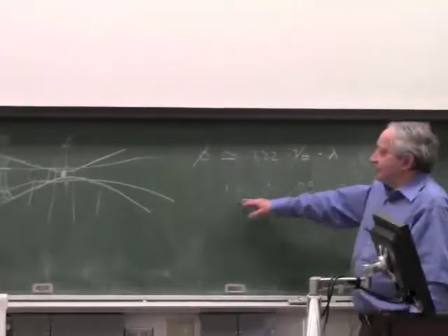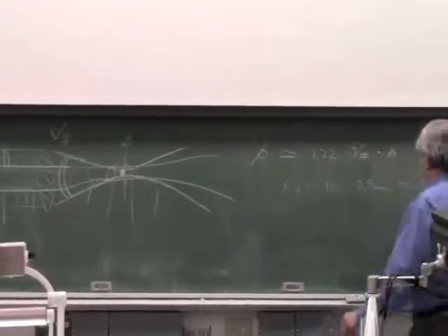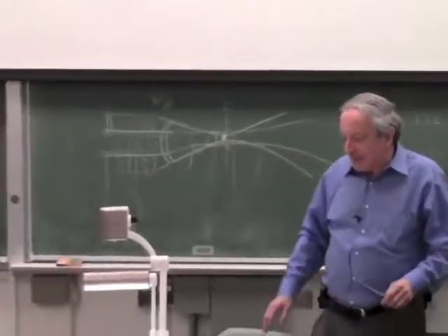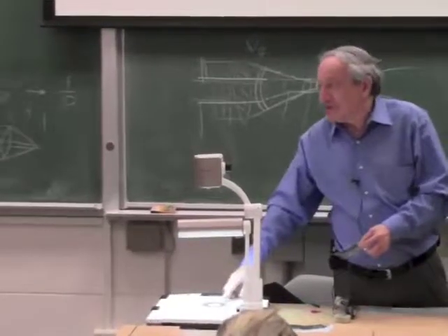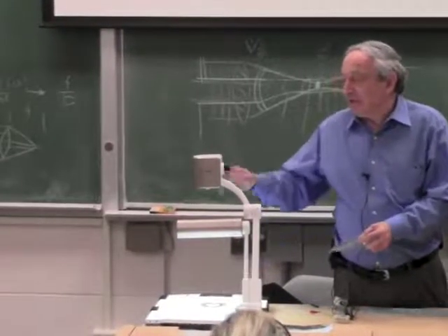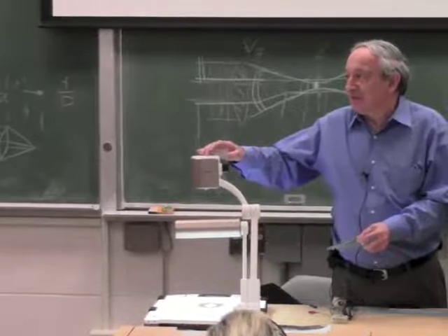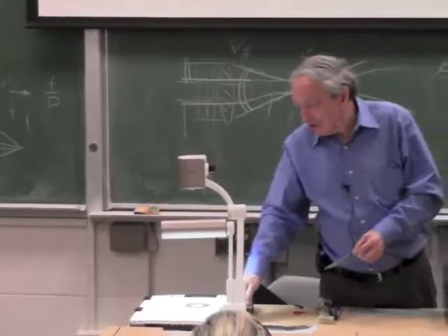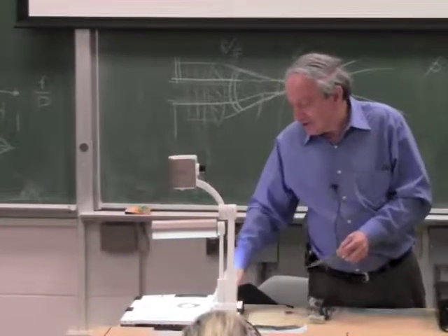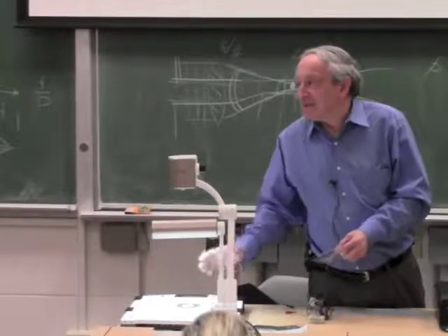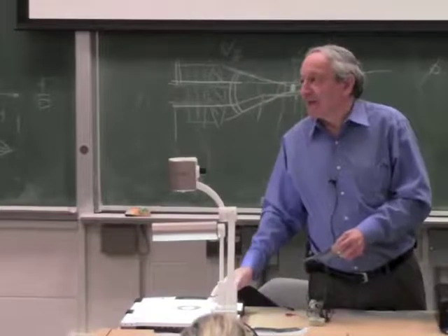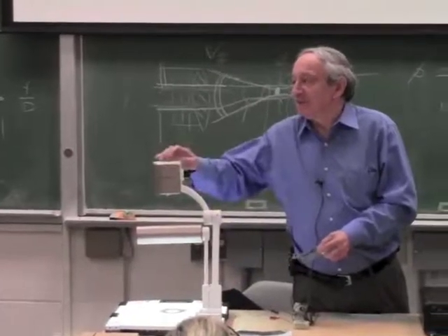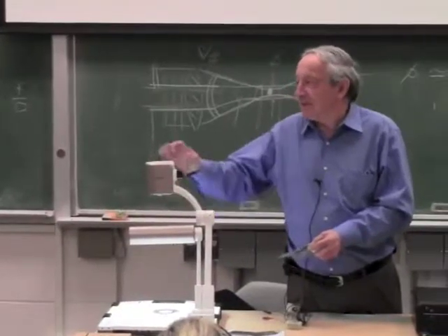Right? Because 5 micron times 1.22, roughly 6 micron. So this camera, the way it's set up, 6 micron is actually very small, if you think of it. Probably the limit will be the CCD, not the lens. Because 6 micron means if I have here 6 millimeters, it's already 1,000 lines. So here it will be like 10,000 lines, which is much more than CCD cells. So the limit here will not be the lens, it will be the CCD.